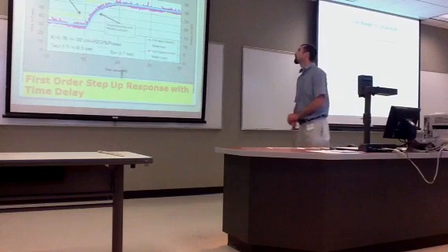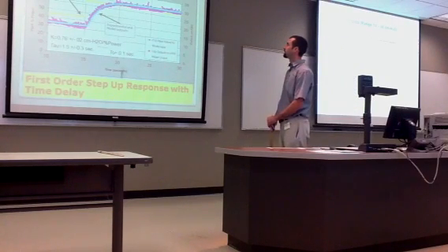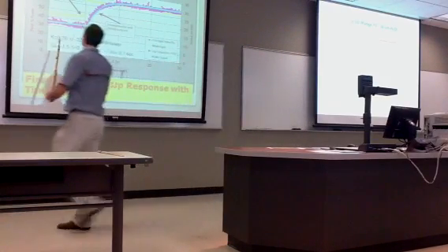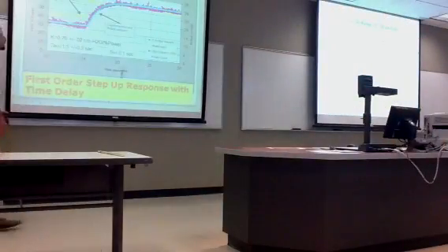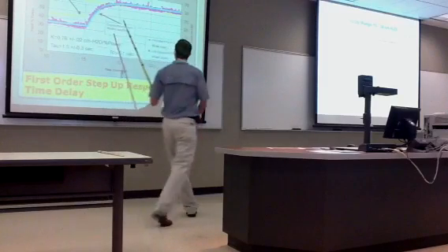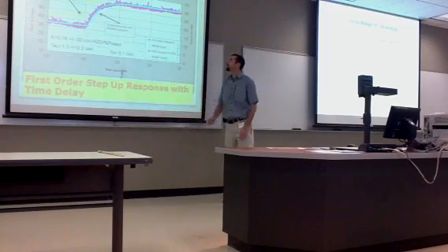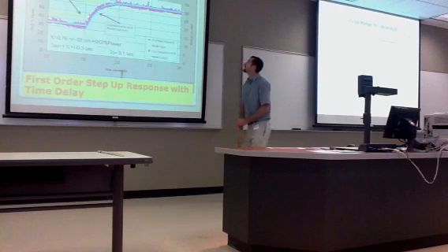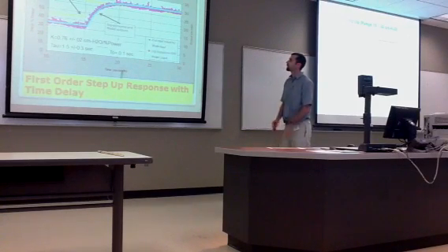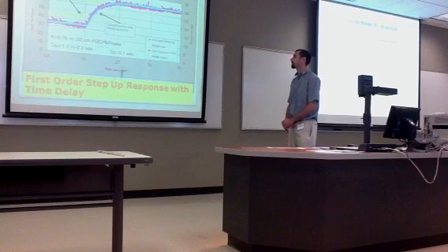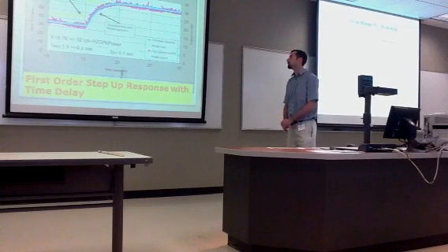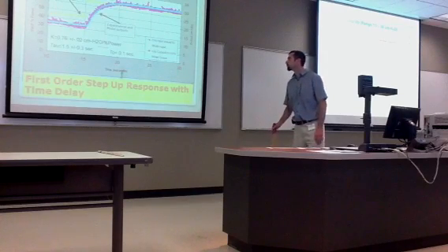resulting in this graph. This is from the range of 15 to 30 centimeters of H2O. We have experimental and modeling input, which fell right on top of each other perfectly. And then we also have experimental and model output, which lined up somewhat well along the curve. Our K value ended up being 0.76 plus or minus 0.02 centimeters of H2O per percent power. Tau was 1.5 plus or minus 0.3 seconds, and T naught was 0.1 second.